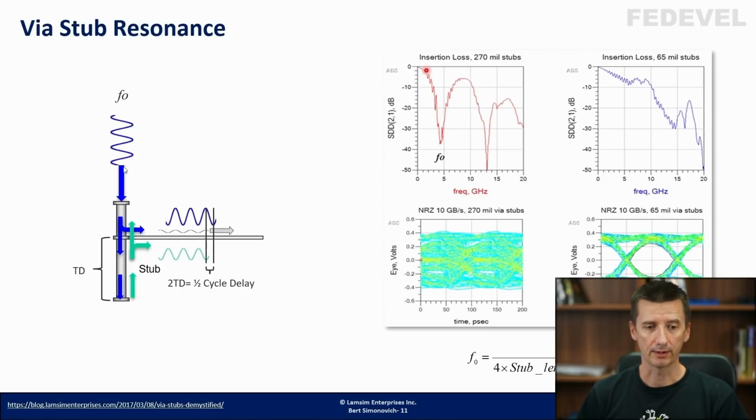Okay, you know that when you are running digital signals through your tracks, it is actually not only one frequency, it is multiple frequencies in this signal, because a square signal contains a lot of different frequencies. And from this graph, you can very nicely see which frequencies are going to have problems with this kind of stub that we can see here.